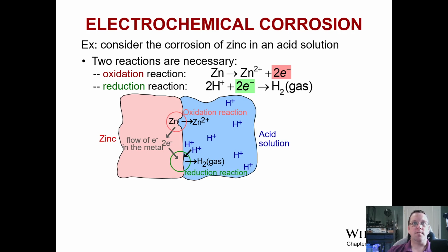So in the case of zinc and just about anything else, zinc is able to give up these electrons and sit comfortably in a lower energy oxidized state, having given up those electrons. This is part of the reason why we use zinc in all kinds of galvanized steels and things of that nature, because it freely allows for giving up its electrons rather than the iron having to do so, which prevents some of the further oxidation. And we'll look at some of the strategies and layering that goes into this.